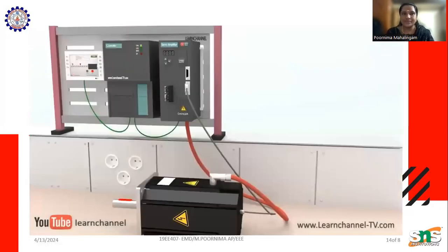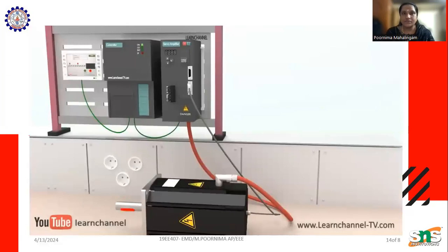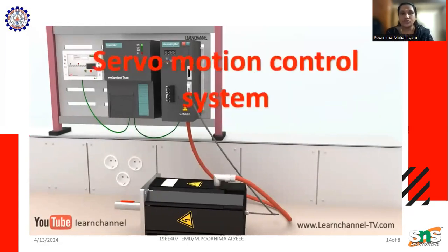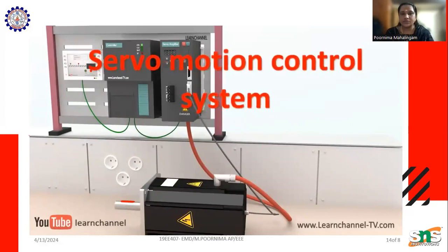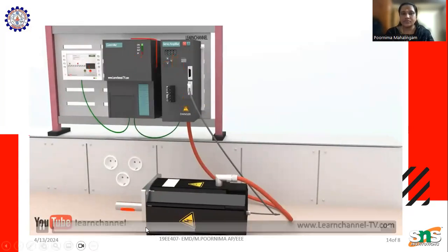The servo motor system includes the servo motor with its feedback device, a servo amplifier, and a controller. But how do these devices work together? These are the servo motor control systems. The servo controller sends low voltage control signals for position, speed, or torque to the servo amplifier. Now these commands are amplified up to high power, which goes to the motor. The electrical pulses of the feedback sensor are sent back to the amplifier. The amplifier uses this information to control speed and rotor position.